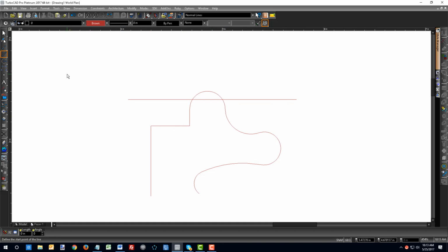They're very accurate, so I'm not quite being precise, which is going to be hard if I'm just freehand drawing. So in the case of a line tool here, if I want to be exact, I can define the start point of my line by hitting the Shift and Tab keys. This enables the X field, and I'm going to type 4 in the X, and I'm going to type 4 in the Y, and then I'm going to hit Enter, and that has now started at a point exactly at 4 and 4 on the X and Y coordinate planes.